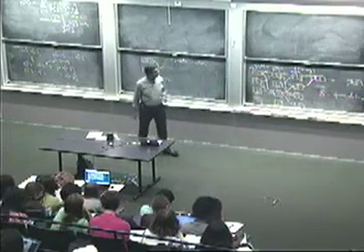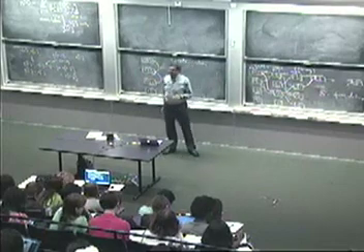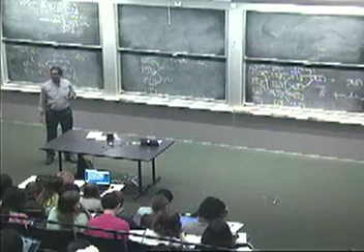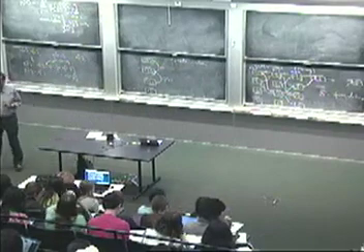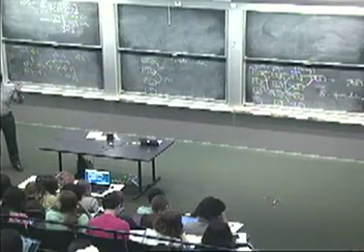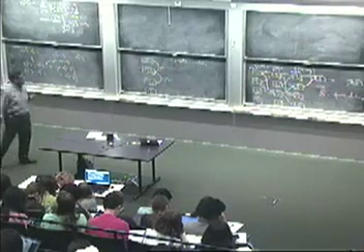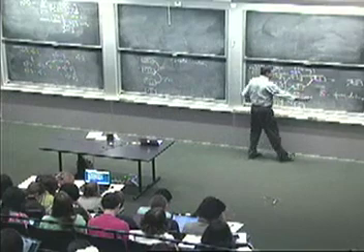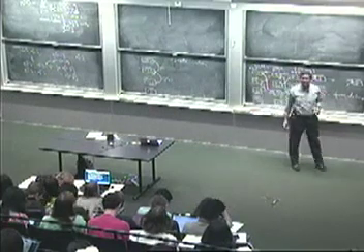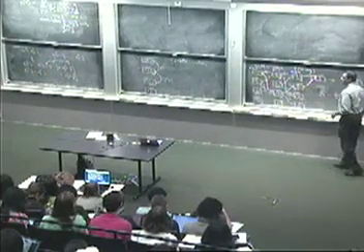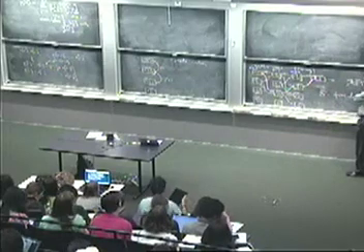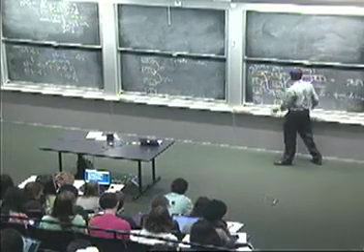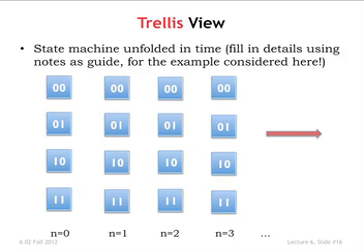Okay. So that's all very hand-wavy, but that's all we're going to do with the notion of free distance. So this is more complicated to deal with than a block code, but the free distance actually has that kind of intuition. It has the intuition of minimum Hamming distance locally, over this window of data. Even if this went on for thousands of bits, if you got a burst of errors in this stretch that had up to 2 errors, you could correct them.